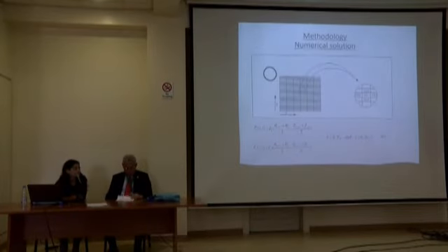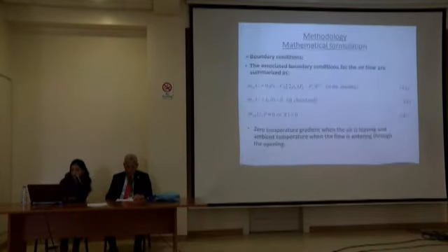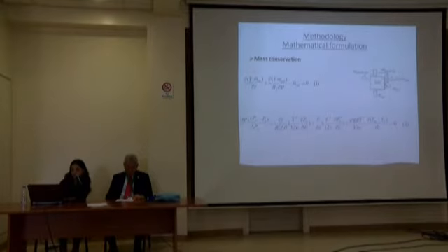Now, after writing the pressure equation and the energy equation, we will discretize them using the finite volume methodology, where the pressure and temperature are discretized using central differencing. From the pressure equation, we will get the pressure of the microclimate air layer, assuming that the temperatures are constant.